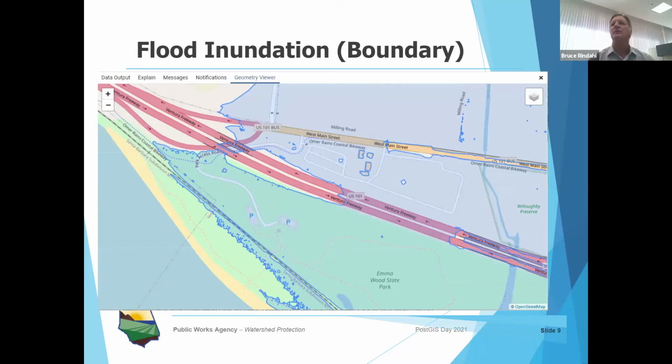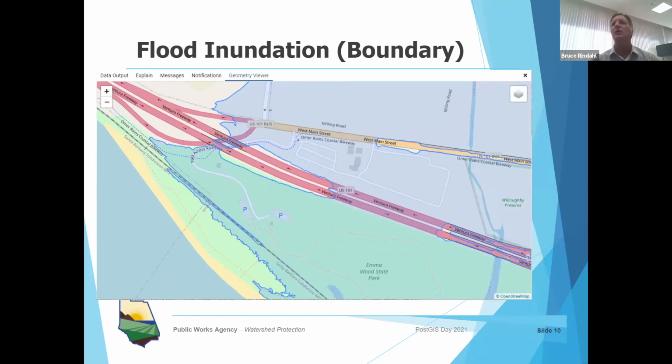Then we can take the inundation boundary from those shapefiles and say, well, there's an outline of it. It's, as we said, a little choppy. You can see some small holes because it's very flat in this area. There are additional holes here, a choppy cross section, and some other information that we want to clean up. With some magic of PostGIS, we clean it up, remove all the holes, and get a much smoother boundary. And that's a pretty standard SQL command that we have worked with and played with. So we can go from a rough estimate back to a smoother one in PostGIS.